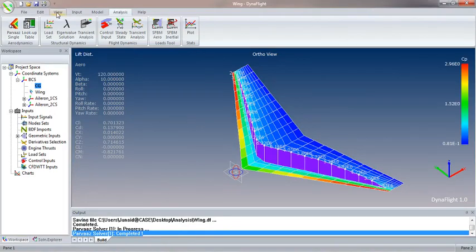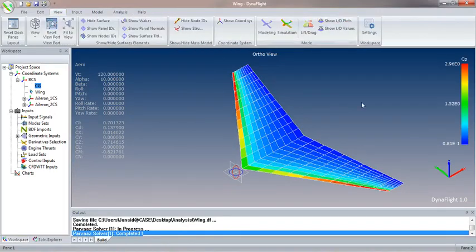We can immediately see the pressure distribution over the wing, with a pressure coefficient legend on the right side of the screen. On the left we can see the input parameters in the top column, and results in the bottom column. The results calculated for this analysis are the lift and drag coefficients, calculated in the wind axis, and three force coefficients Cx, Cy, and Cz, calculated in the body axis, and the three moment coefficients for roll, pitch, and yaw moments, denoted by Cl, Cm, and Cn.